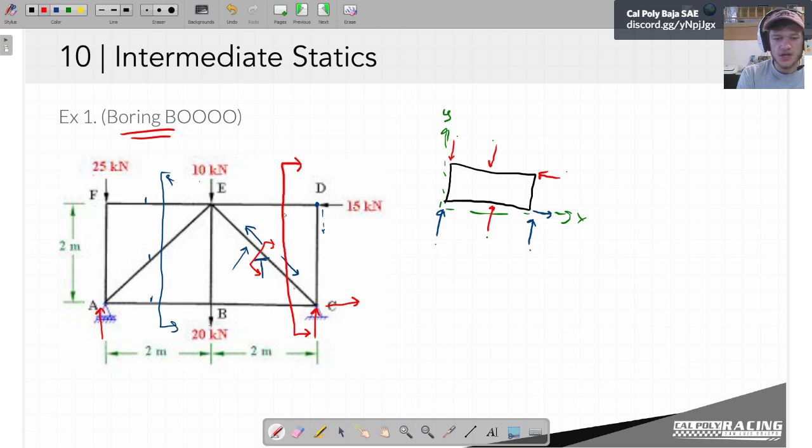If you just cut a body in one place, like if we were to just cut it here, well, then we have some problem that looks like this. So we've got something that looks like that, and some force just floating around in the middle here. And this is now an internal force. So we run into the same problem that we had before we even started talking about these advanced methods, where we're solving for an internal force with external constraints.